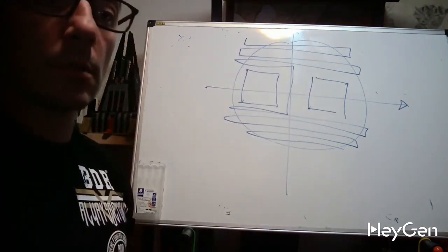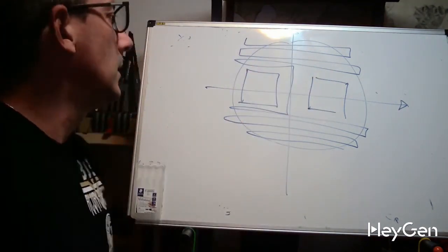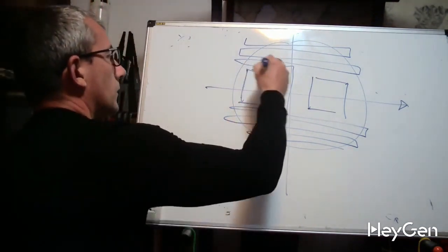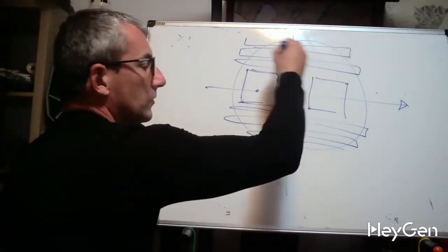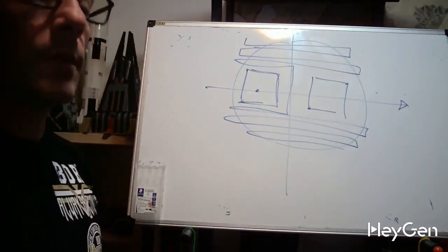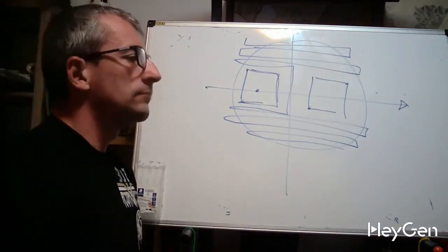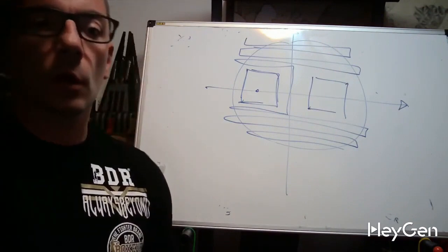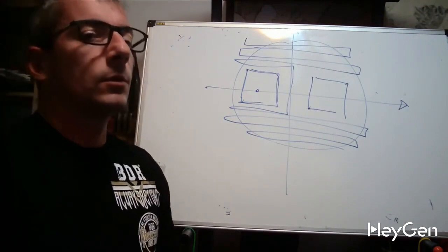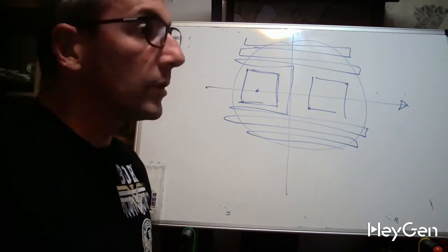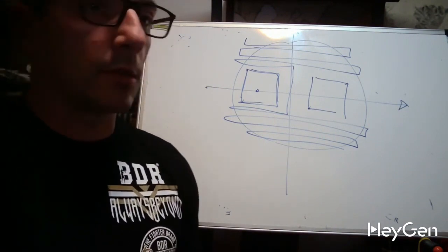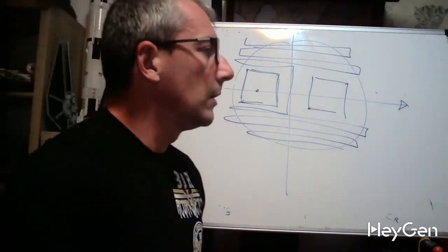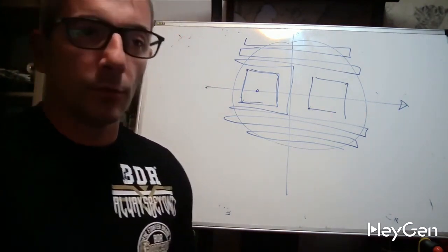Because to program this, you can also create a sub-program and then shift the origin, but first you need to clean the workpiece. And that's the slightly more annoying part of milling. Millers aren't as fortunate as turners with macro roughing cycles. I misspoke about mills lacking macro instruction cycles. With lathes having ASC, you can't just provide two profiles and expect a macro to handle everything.